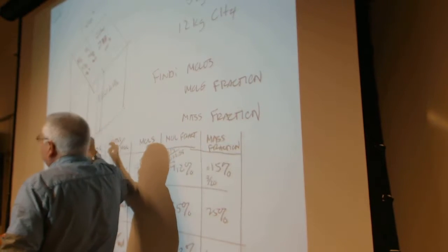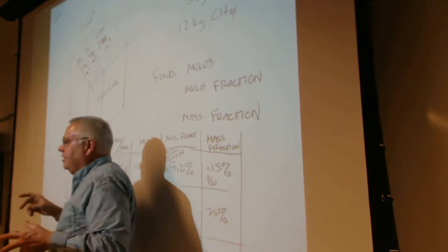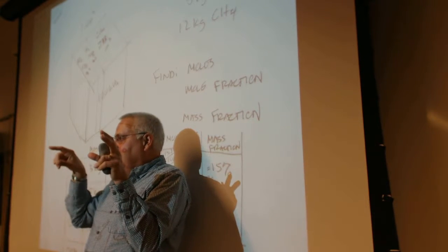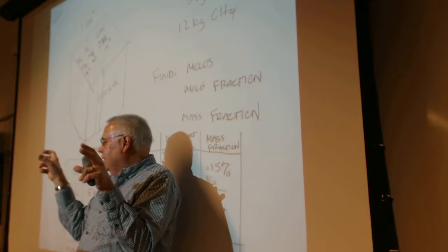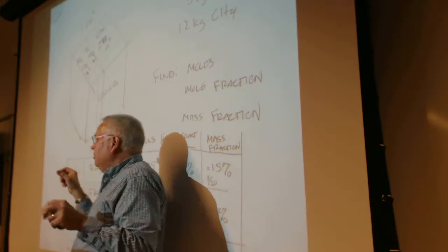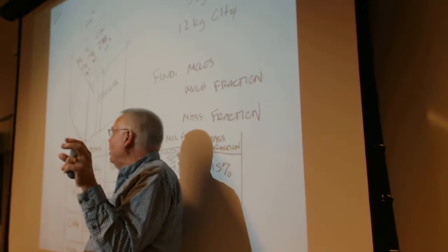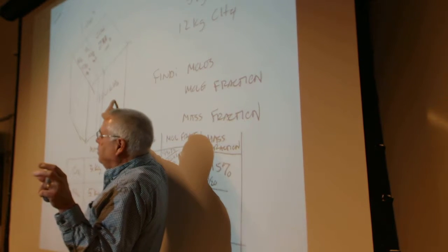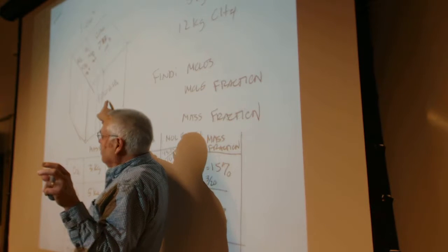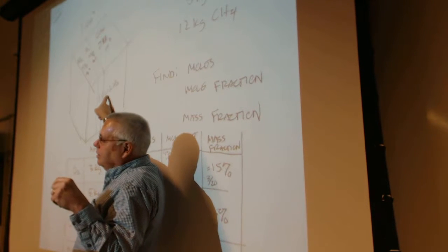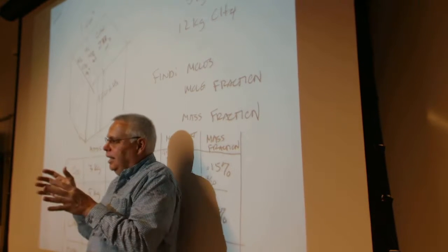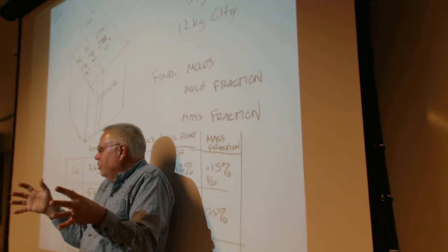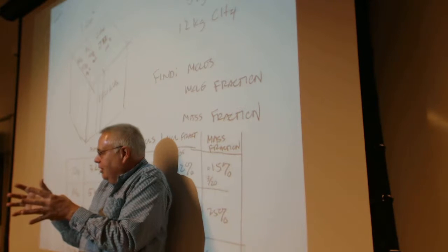And now I do like the magician, and I cut these and have these slices, and if they were all at 100 kilopascals at these volumes, ideal gas law says PV equals nRT, and if n is the same and the R is the same and the T is the same, that's a constant. So P times V, well, if I take this one here that was 73% of the total volume, that's 100 kilopascals. And now I take it and expand it out to 1 cubic meter. It was 73% of a cubic meter at 100 kilopascals.